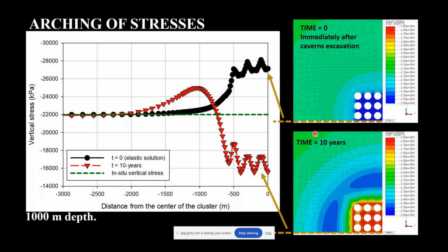And this is the vertical stress at time equal to 0, before any creep deformation, and this is after 10 years of creep deformations. What is quite interesting is that just after dissolution, the vertical stress at this cross section increases. It's larger than the in situ vertical stress. However, with time, this changes.